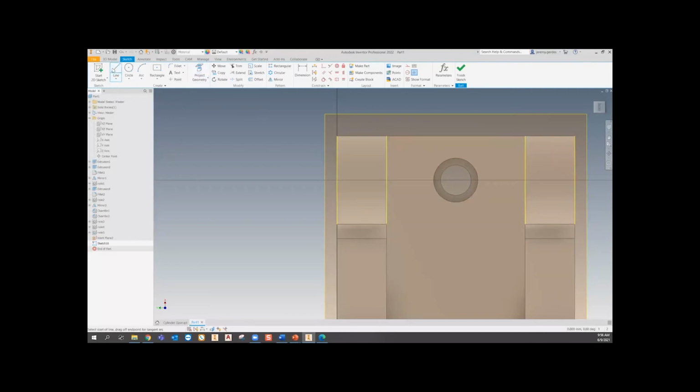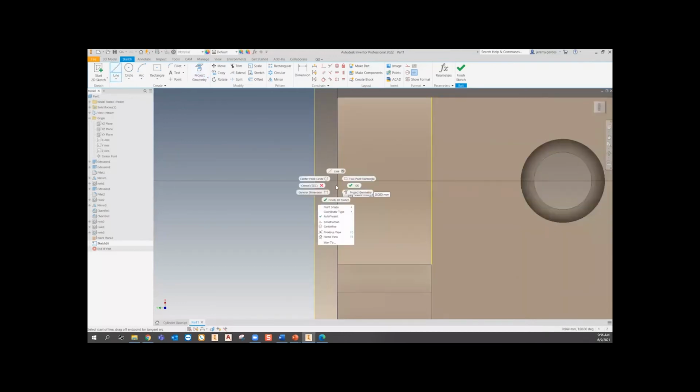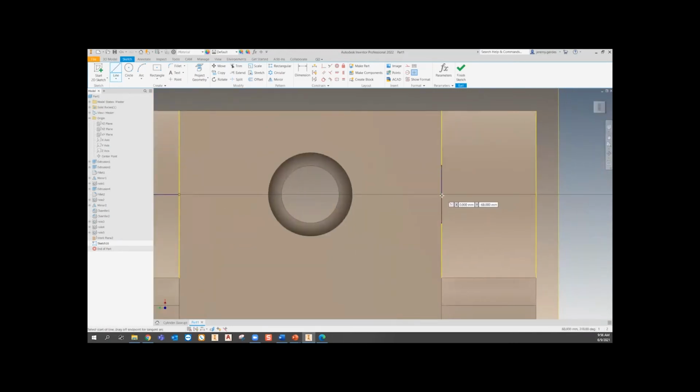And then what I would do is start a new line. If I right click, hit point snap, hit midpoint, it'll automatically make sure it goes to the midpoint. And you know, most times you can tell when it snaps to the midpoint, but in cases like this where it is on interesting geometry, I like to make sure I say I want it to be the midpoint. Okay. And then what I'll end up doing is adding a point to the middle of this. So again, midpoint.